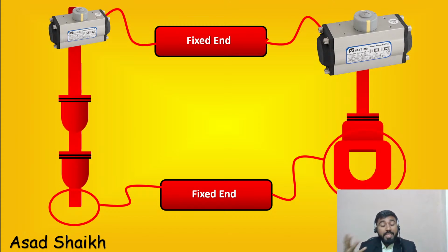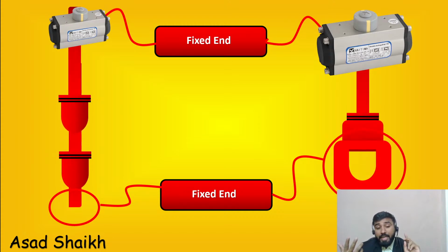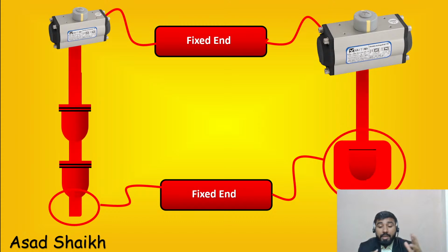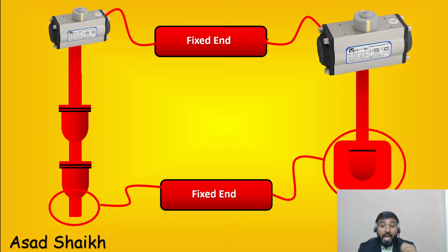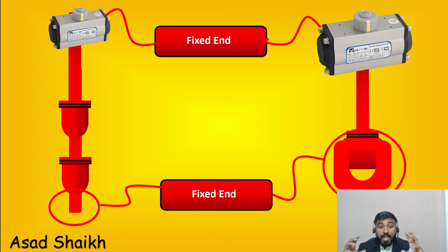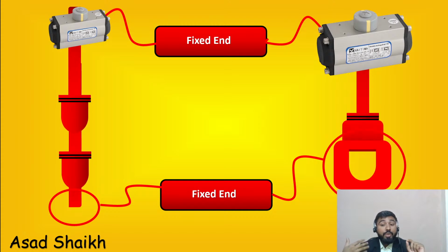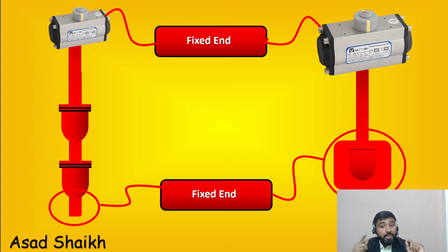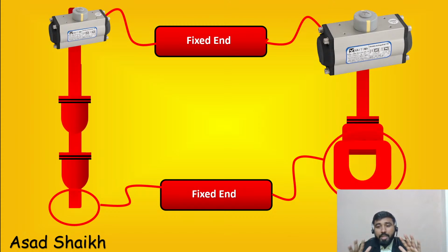So now you have better stability at high differential pressure applications, and this reduces the leakage paths. This reduces the need for a bigger design or two ports. Also the space requirements have reduced, so this seems to make a lot of sense. However, there is a big however. If your service has big solid particles which could get plugged into your cage, then maybe you need to still think about dual ported design. They are not traditionally used. Most applications you should avoid them.